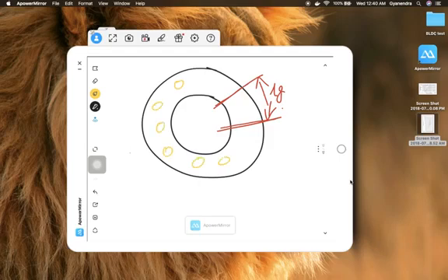Instead of a lumped air gap, the whole air gap is distributed throughout the core. It is done using non-magnetic materials inside the core, so that we get the suitable reluctance required for meeting the inductance specification.